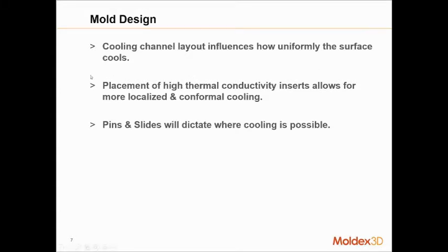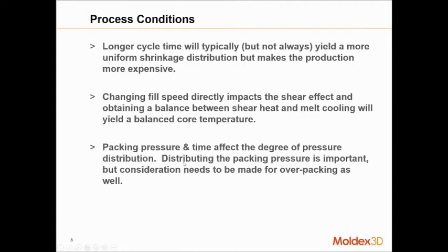There's a lot of innovation and a lot of different inventions coming out of the conformal cooling world, especially with the emergence of 3D printing. It makes things a lot easier to create more complex cooling systems. And like I mentioned earlier, pins and slides will always dictate where the cooling is possible. So your mold design ultimately will dictate where you can place your cooling, and your cooling placement will ultimately influence the uniformity of material shrinkage on the surface of your part.